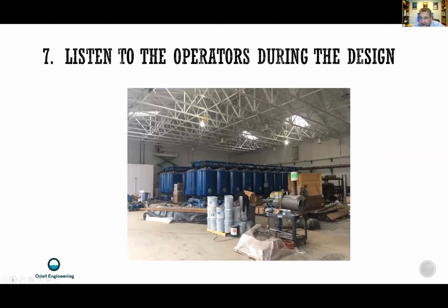Listening to operators during the design is really important. Especially if you're working with a utility that has a similar treatment plant already, they're going to know what they like and what they don't like, and that's really valuable information. If you're working with a utility that doesn't have a similar treatment plant, I love taking people to other treatment plants, talking to the operators that have similar facilities, asking them, what do they spend their time with? What do they wish was done differently? It's just really, really good information.